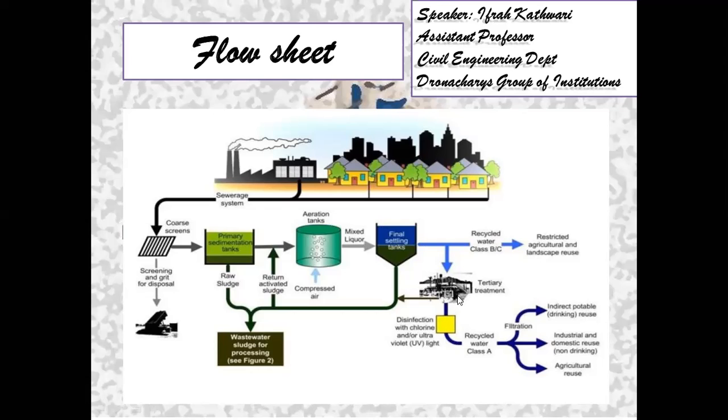Here also we come up with sludge, and again it is moved on to treatment and processed well. The water from tertiary treatment is further processed by disinfection, wherein chlorine is added and it clarifies the water further.